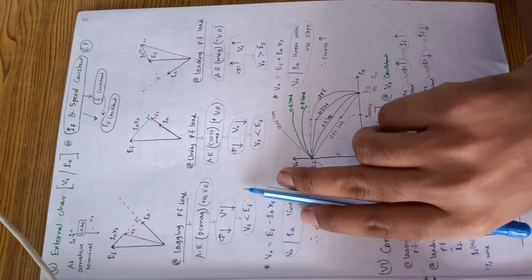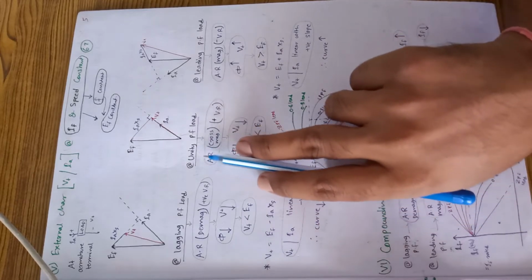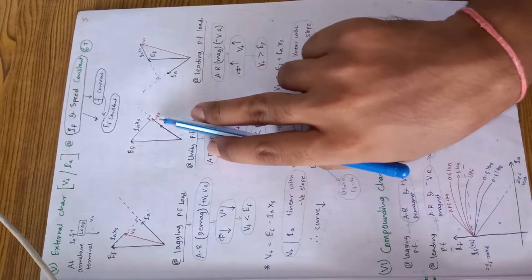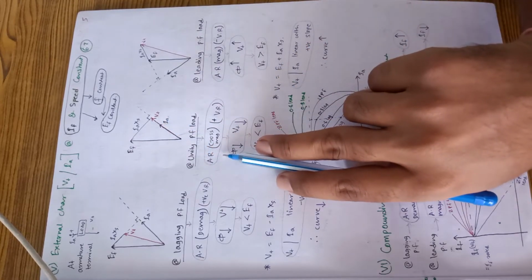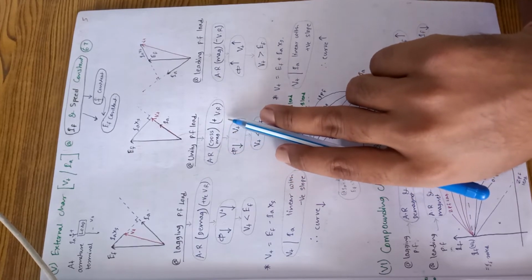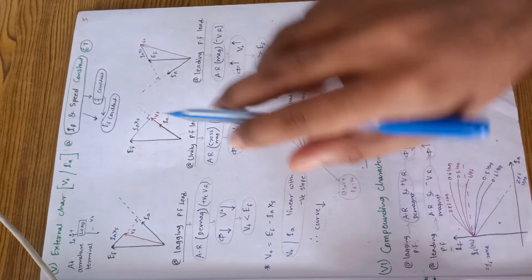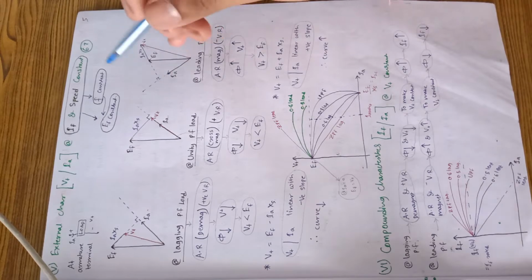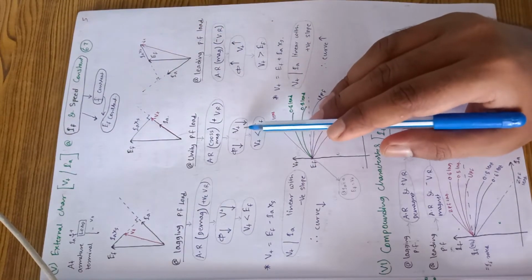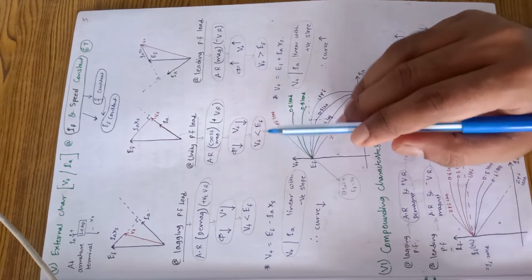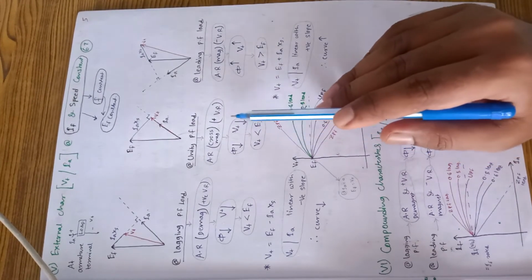In the case of unity power factor, the current will lie in the same phase as the terminal voltage. The armature reaction is cross magnetizing, which is positive voltage regulation only. If there is cross magnetization, the flux will decrease, so Vt will decrease, and Ef is greater than Vt. This is also the case of positive voltage regulation. Unity power factor means positive voltage regulation.